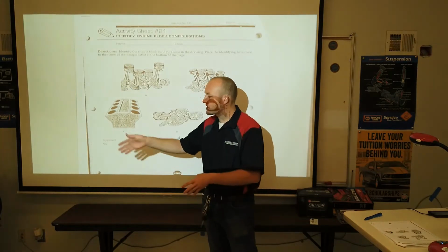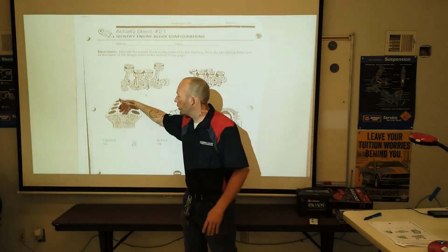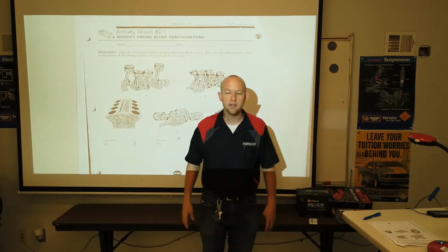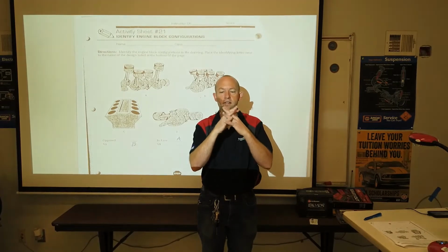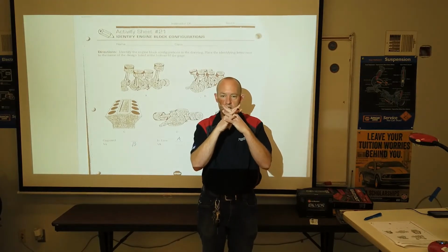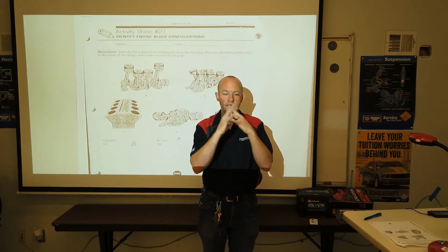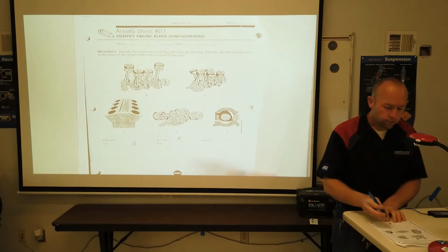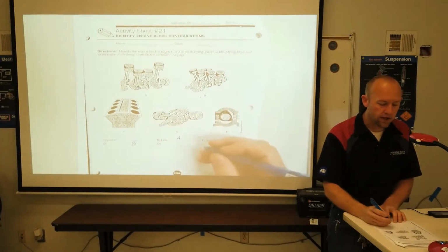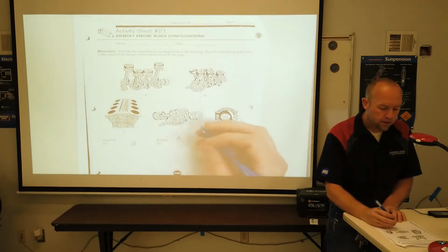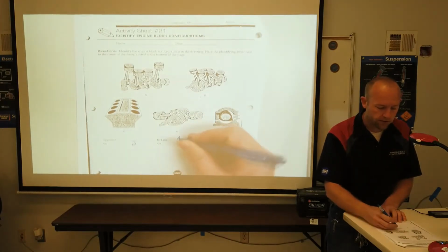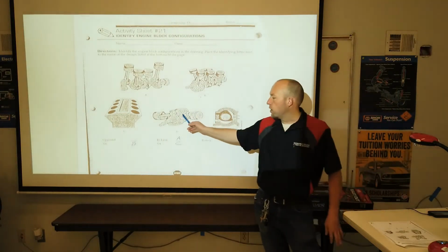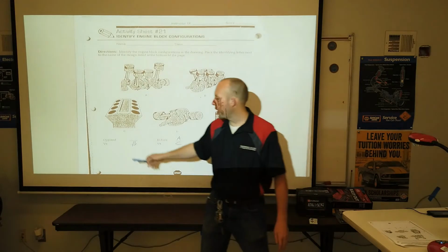If you look down the side of any V motor, you'll see that one cylinder head will always lead the other by at least the width of a connecting rod. It has to do with the fact that the cylinder head covers the cylinders, and the cylinders have to be offset because of how the connecting rods are connected to that crankshaft. So there's our V8, and we know it's a V8 because we can see the bores in the block. So 8 bores in the block, or cylinders in the block. So that's C. Then we get around to this style of motor, which is an opposed.